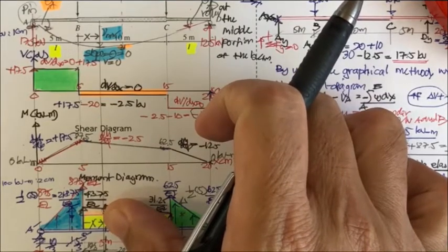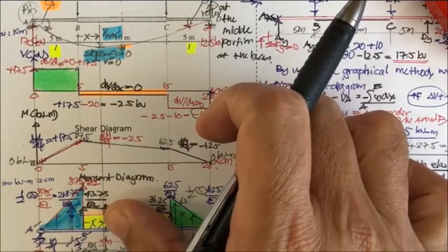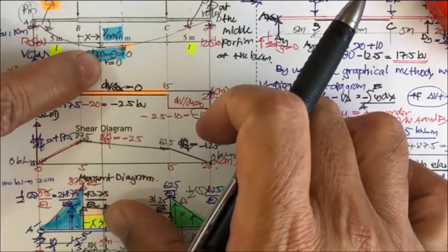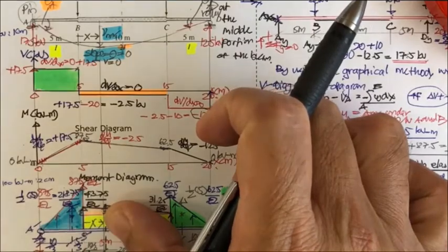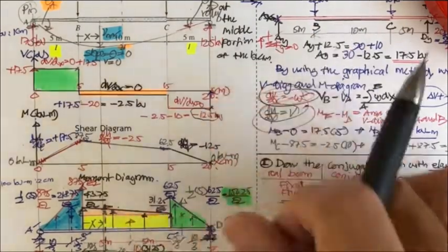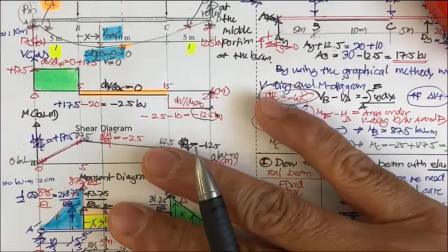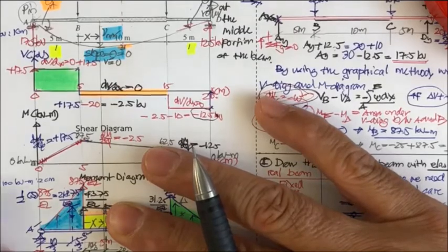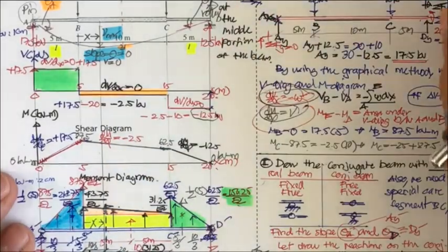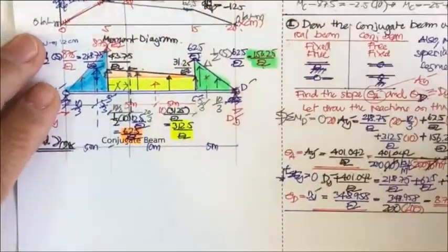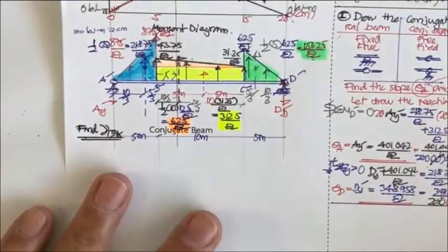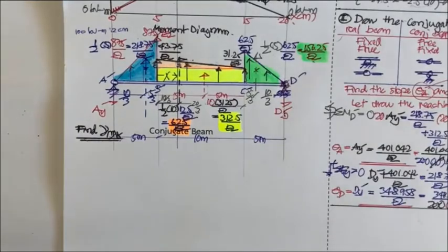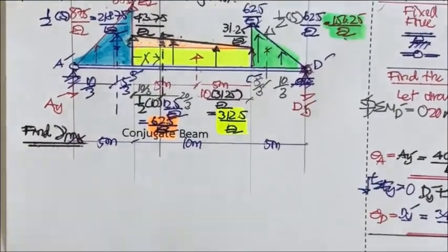Okay, and for me, I'm going to use this portion, with the condition that the shear force in this section is going to be 0. Okay, let us consider the free body diagram of this portion of the beam, and let me move this one, and we're going to zoom in because there is going to be a lot of detailed calculation here.